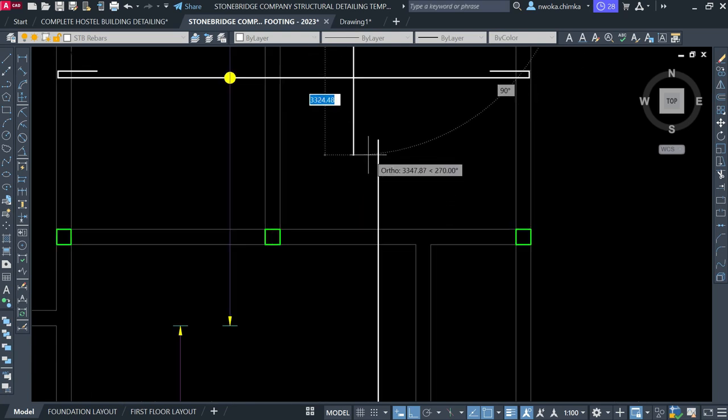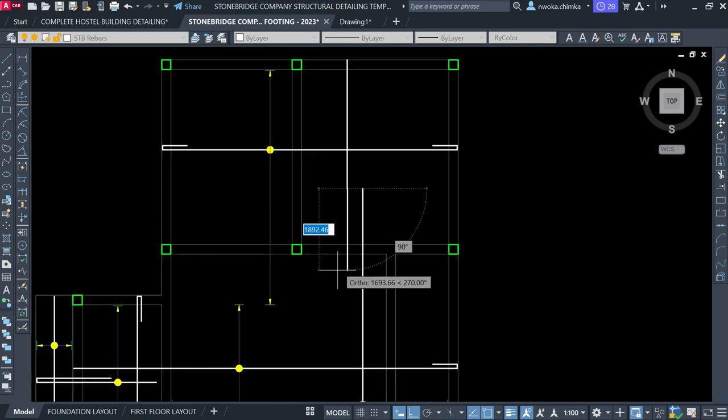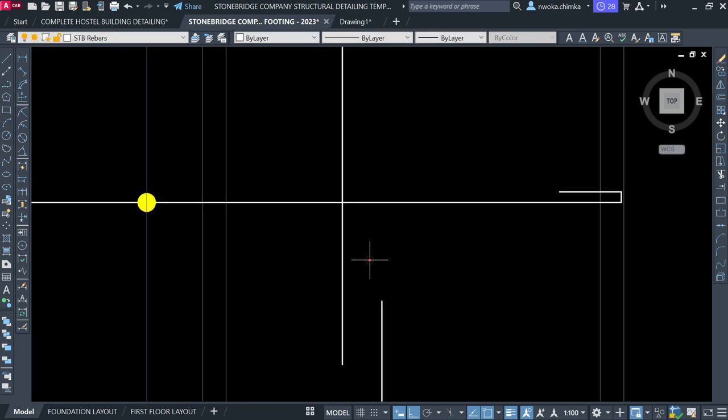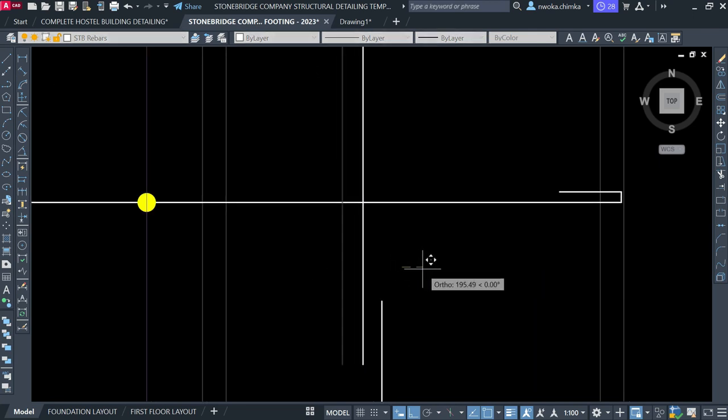Okay, so I'll first of all keep it here and make it here. Okay, that's fine, you can see that. Then I'll give my lap length of 600 first, 600 here, using the rule of the code. Okay, and then move it near to the reinforcement first.